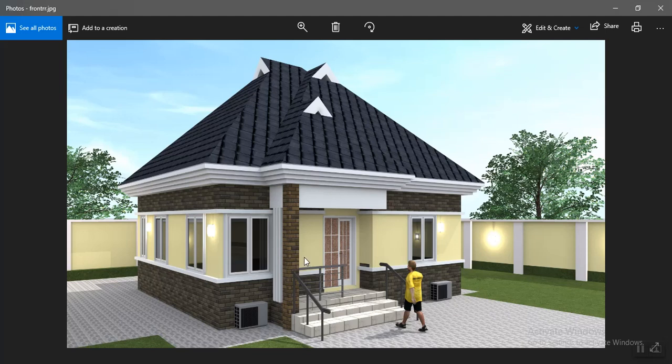So the next thing we're going to pick right now is this. We want to pick out these external walls, because if you check the 3D, they're already rendered in 3D. You will find out that there are 2 walls in this spot. There is the major wall and there is this bricks design. So we're going to create this wall and this wall. And from the view here, we'll find out that this wall terminates on top of this window and under this window. So let's first create this extra here.